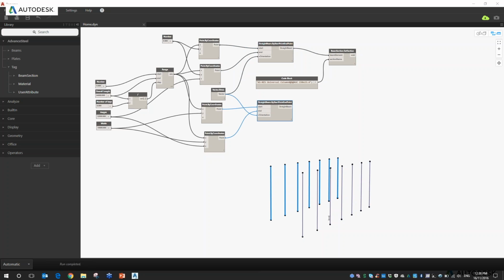So your workflow might be that you do this in Dynamo for Revit, create your frame and your base structure in Revit, and then export that to Advanced Steel and then detail it. You do have the 2-way synchronization between the 2 still, but again, keep in mind if you change something from the Revit side to the Advanced Steel side, depending on the connections and what's happened, you might need to redo those connections again. So I guess it's something that you'd work through, depending on your workflow and at which point you come into the project and whatever your scope of work is as well.